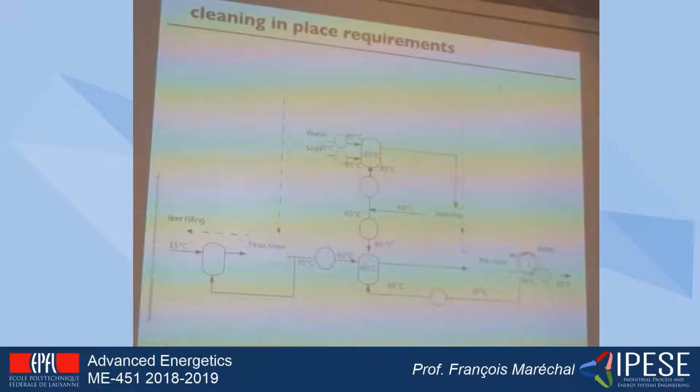And it's leaving the system in the form of dirty water that is going to go to the wastewater treatment. And I can use the heat that is available there for the heat recovery as well, meaning that I'm going to define a new hot stream that goes from 40 to 20 degrees C.